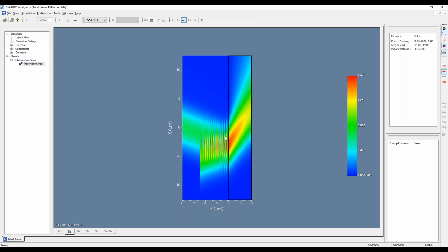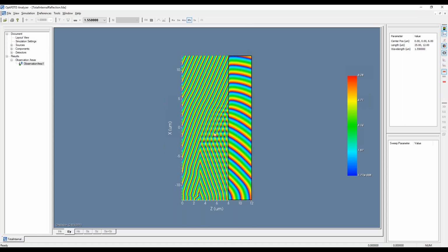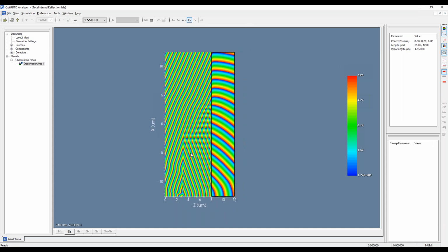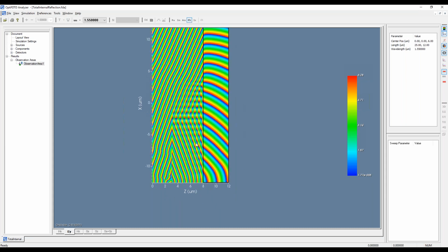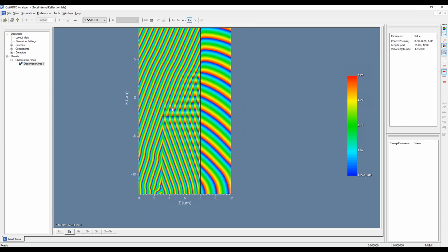You also see that the beam is diverging on the right side a bit because it's a Gaussian beam. And let's see if our notion of phase change is proper. Are we doing close to a plane wave simulation? So I switched to phase here, and you'll see that on this side there's an interaction in this area between the reflected and the incident wave beam. But down here it's very close to a plane wave, right?